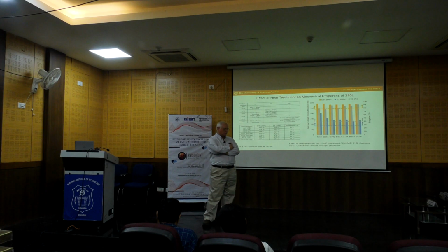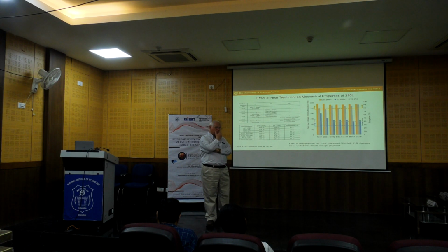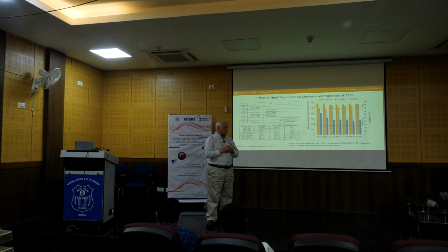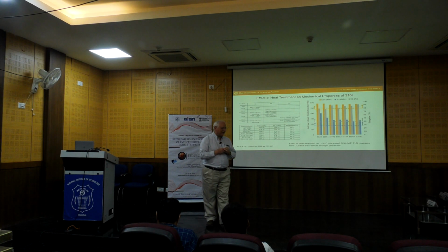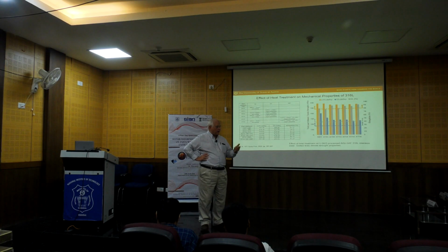What I've seen people do with metals: it turns out there are one or two standards dealing with recycled metals. For certain applications it's not allowed, so the material must be virgin material. That solves the problem, but it's very expensive. Perhaps the easiest solution, at least in part, for satellites is to take the powder and re-sieve it before putting it back in the machine.